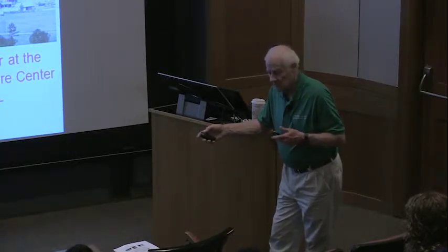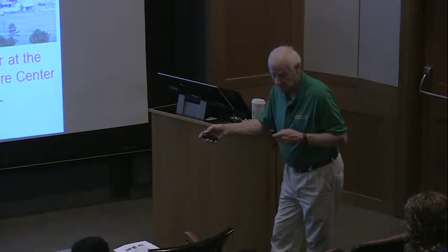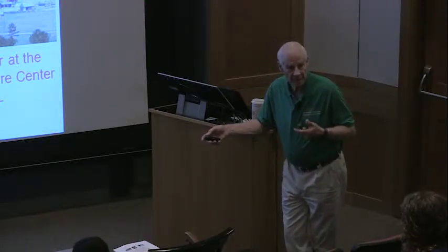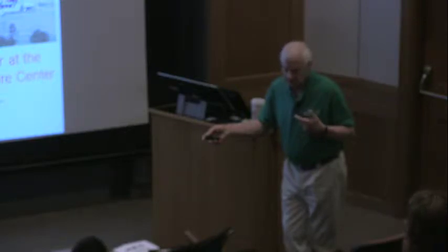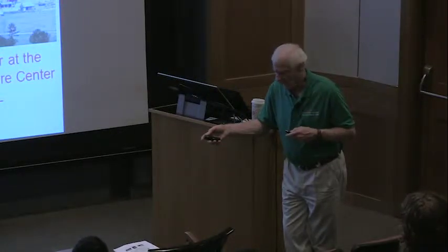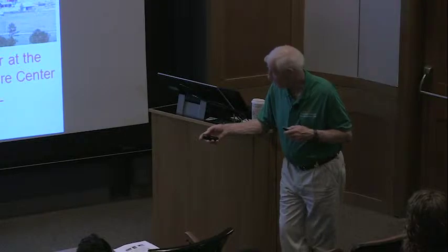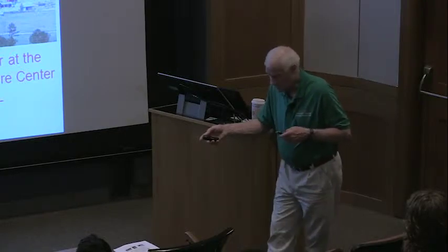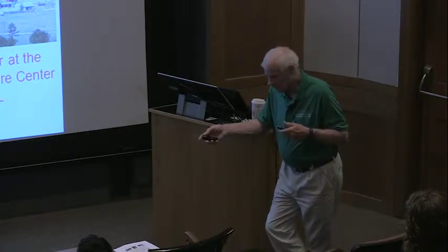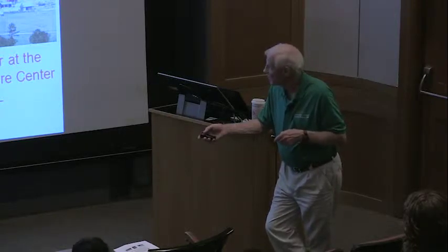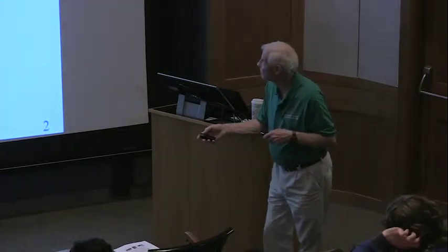First challenge being, can we make measurements at, say, 15 or 20 atmospheres? What happens at 15 or 20 atmospheres is that the lines become spectrally broad. And so problems with interferences from other species or other transitions come into play. So we have to have a code that allows us to calculate the absorption coefficients as a function of pressure, which means we had to measure the pressure broadening coefficients, and we had to be very aware of interferences. You'll see that. I'm going to start with IC engines, just because that's something that we're pretty successful at.